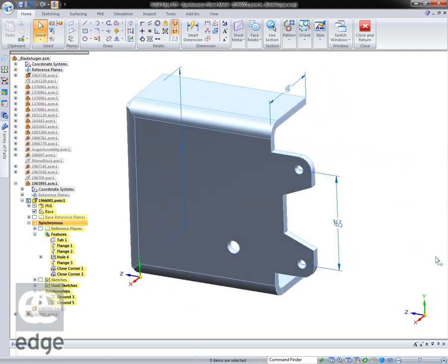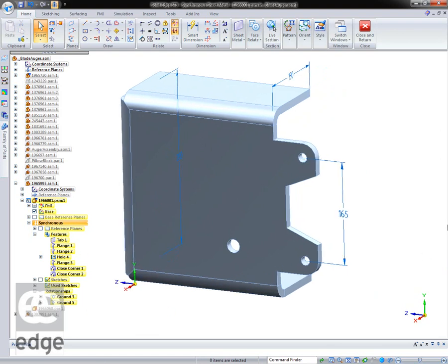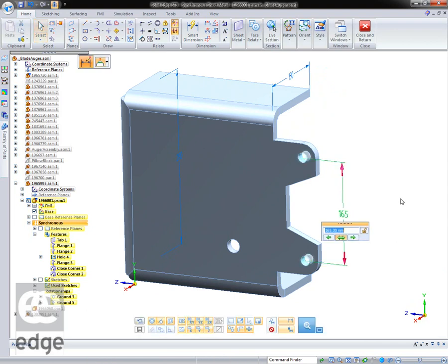We'll notice that this part is not symmetrical. We've got our base coordinates down here in the corner. Now, if I select that dimension, it's been selected before to be the symmetric dimension. I can do that either way, but I want the symmetric. Now, when I do a symmetric dimension, what it's going to do is apply local symmetry. Let me just roll the cursor and you can see that happening. Pretty smart. Let's make that 120.